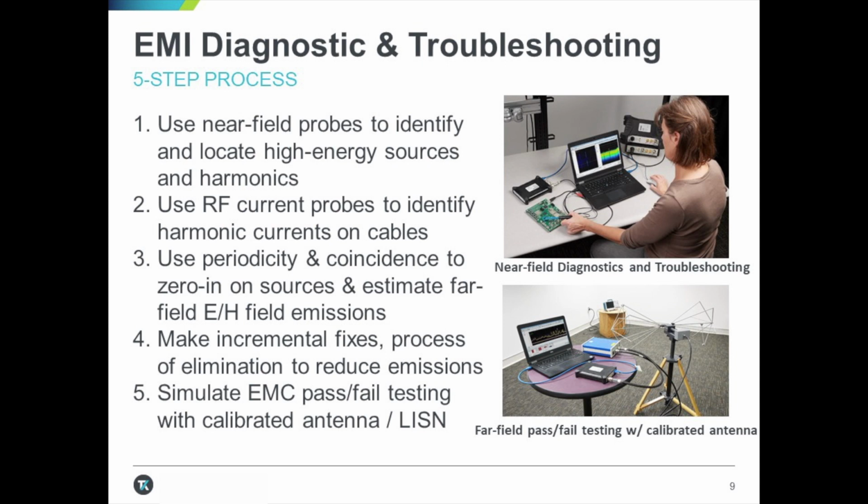While there are many different scenarios depending on the EMI standard you're testing for, here's a do-it-yourself 5-step process for performing EMI troubleshooting and pre-compliance pass-fail testing of radiated and conducted emissions, much of which can be performed using a powerful yet affordable real-time spectrum analyzer or mixed domain or mixed signal oscilloscope.